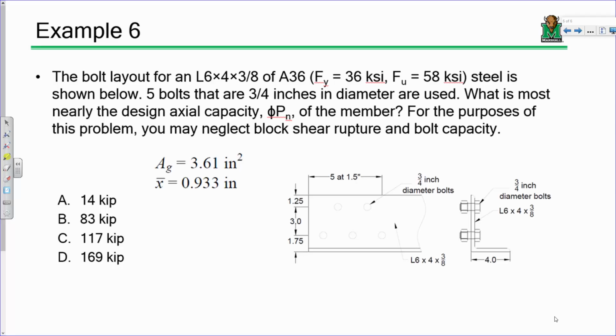And so as a result, it's actually very rare that you would have a tension member that's a wide flange. At least I think so. And the reason why is because remember your shear lag factor, you need the equivalent properties of that WT. Well, we don't have that, so that's a little bit of an issue to work out.